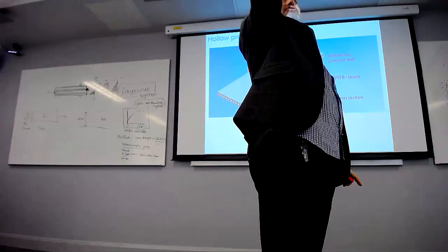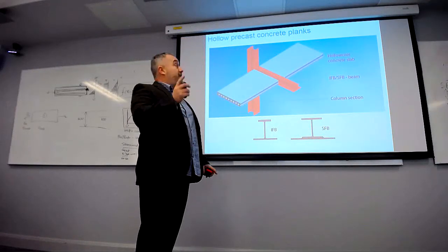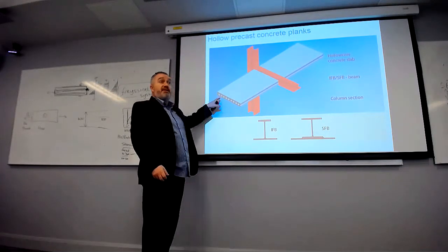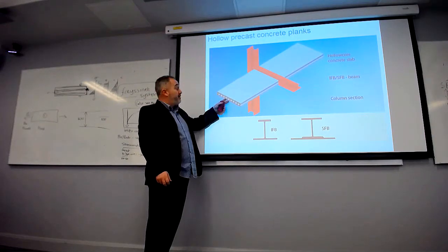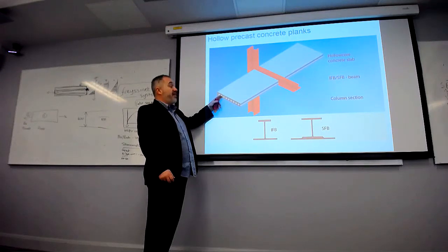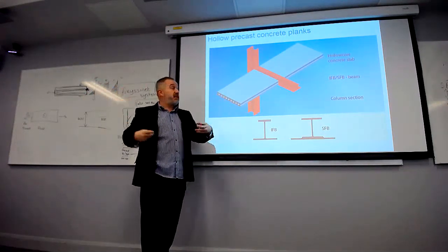They're resting on top of the beam itself. Now, we'll see that these precast slabs can either be solid or they can have holes in. They've got reinforcement in them. The ones that are hollow precast slabs are lighter, so therefore can span further. They've still got steel through.